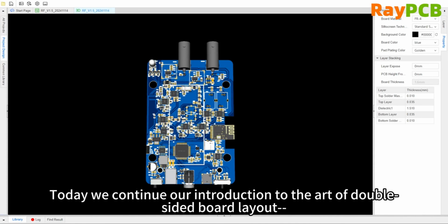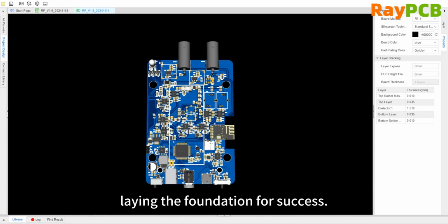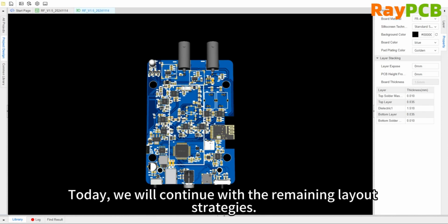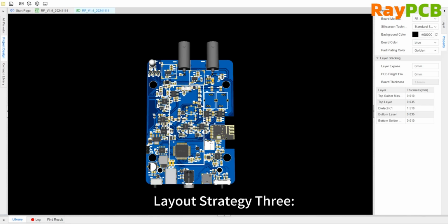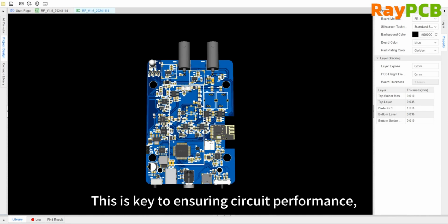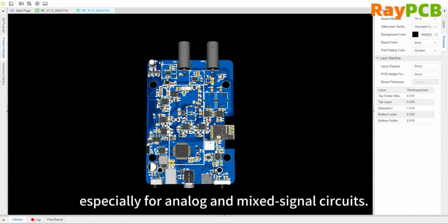Today we continue to discuss the art of double-sided PCB layout, laying the foundation for success. In the previous episode, we introduced the first two layout strategies. Today we will continue with the remaining layout strategies. So, layout strategy 3, isolating signal flow from high noise areas. This is key to ensuring circuit performance, especially for analog and mixed signal circuits.